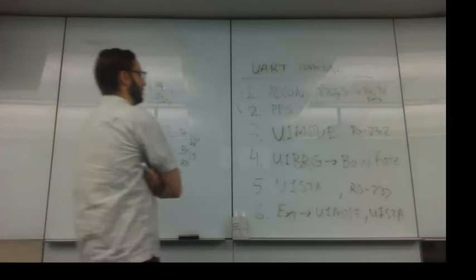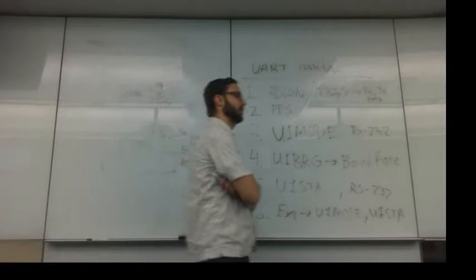So it's like anything else, you do it the first time and it seems complicated, but after you write it once, then you don't really have to look at it again. You could even write an initialization function where you could just pass it a baud rate that you want, and the function could calculate BRG for you. If you're clever, you could maybe even write it in #define directives in C, and so it would calculate the baud rate before it programs the chip, and then just plug in the correct number.